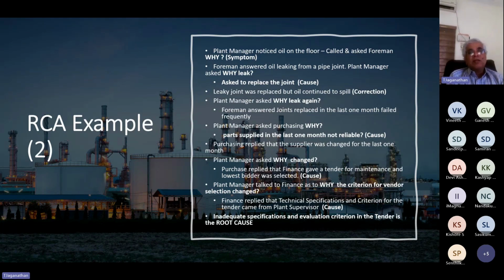Okay, sir. First stage, you come and sweep it. Is it going to solve the problem? Oil is going to drop again. Then at the next stage, we found out, sir, after checking everything, there is one joint which is leaking. We go and put Araldite or M-Seal around it. That leak will stop. But the next day, again oil is dropping, because you have not addressed the root cause.